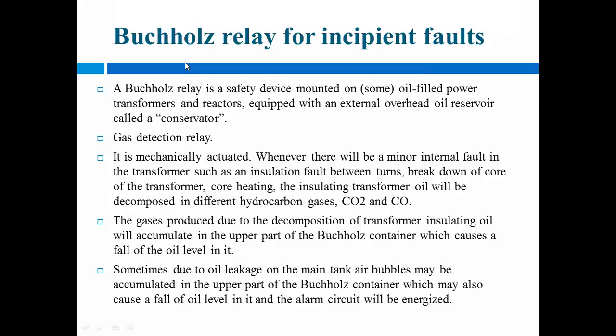These gases are hydrocarbons, carbon dioxide, and carbon monoxide. When they are liberated, your relay will operate. That's why it is called the gas actuated relay, and it is mechanically actuated.